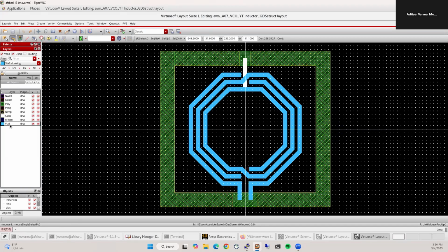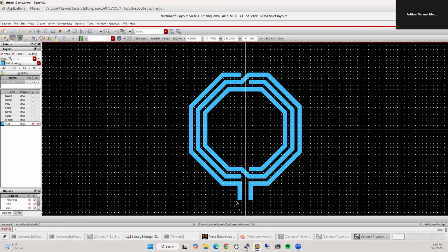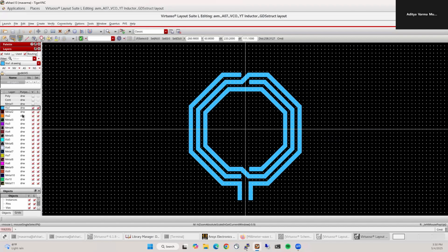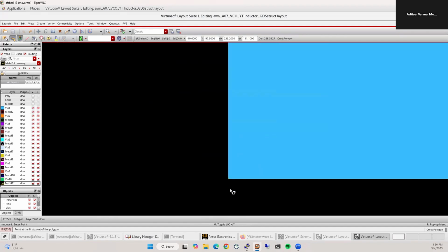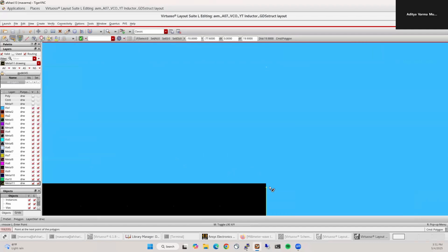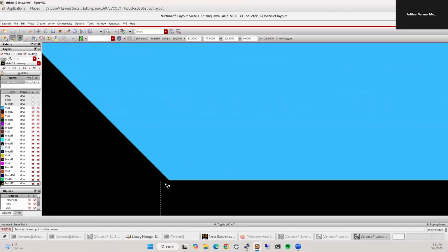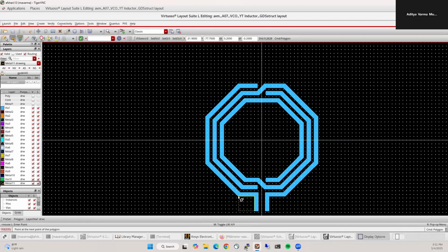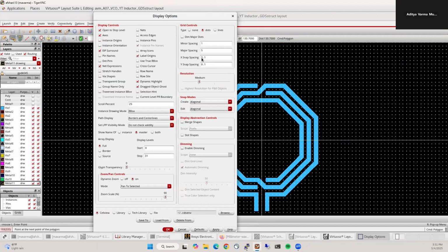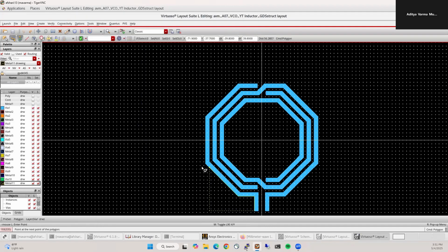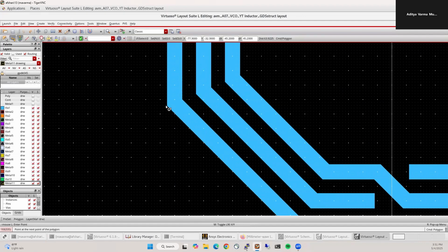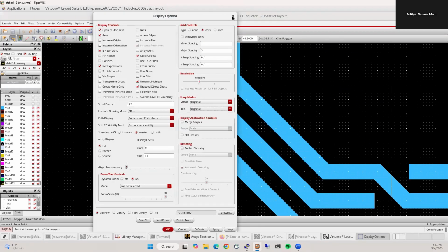So let me show you how. So this is VR1. It shows VR1 to make the M11 layer. Go to routing, select M11, Shift P to draw a polygon, and then I'll draw a polygon on top of this. And make sure you're in the right snap spacing. So here I've chosen 0.1 rather than 5 nanometers because it doesn't really matter. And for diagonals, if you hit E, you need to make sure these are diagonals as well.